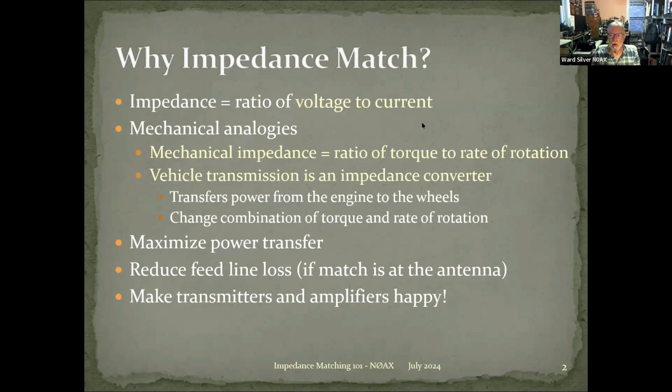Now I have to digress for a second, and people say, you mean that the power generating grid has matched the impedance in the generator to the impedance out there in the grid? No, it doesn't work like that. If you did that, what they don't tell you in the maximum power transfer theorem is that both the load and the generator will then dissipate equal amounts of power. So you do not want to dissipate half of the nation's grid power in the generator. So this is a case where there is no impedance matching at the generator, just a side note.